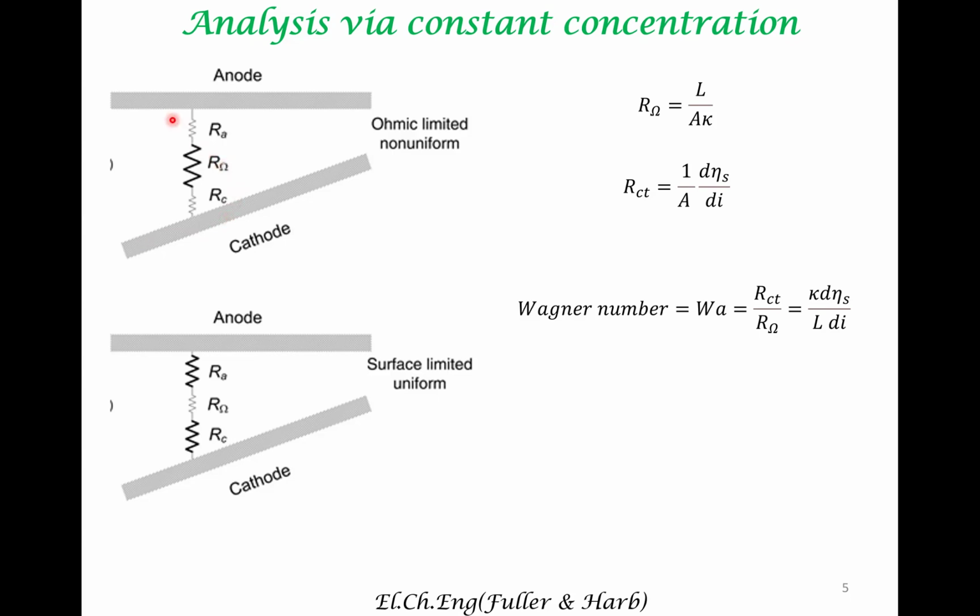So in that case, the metal is taken out of the anode and then deposited onto the cathode. And because of the complicated geometry, the distance between the anode and cathode might differ. So with respect to this process, there are three resistances. There is a resistance associated with the electron transfer at the anode-electrolyte interface.